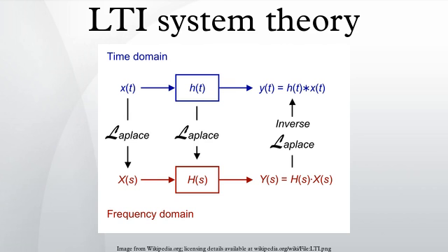The Fourier transform is often applied to spectra of infinite signals via the Wiener-Khinchin theorem even when Fourier transforms of the signals do not exist. Due to the convolution property of both of these transforms, the convolution that gives the output of the system can be transformed to a multiplication in the transform domain, given signals for which the transforms exist. Not only is it often easier to do the transforms, multiplication, and inverse transform than the original convolution, but one can also gain insight into the behavior of the system from the system response.